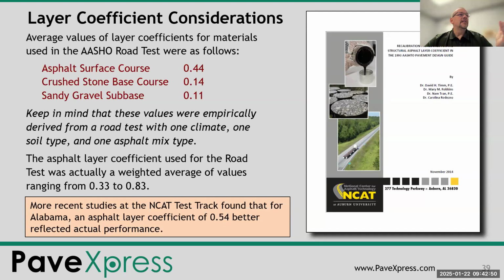And then the layer coefficients for a crushed stone base, like a typical aggregate base, is 0.14, and a sandy gravel sub base is 0.11. These are typical values. Those are the same values that MDOT uses for a dense graded base and their sand sub base.